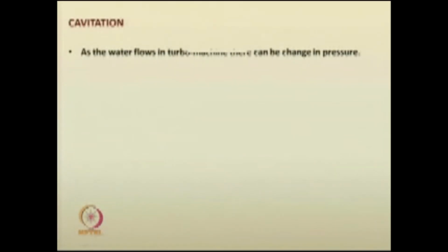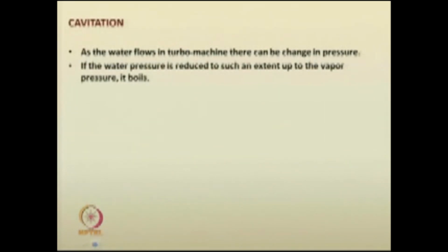Next, we would briefly like to discuss cavitation. What is meant by cavitation? As water flows in a turbo machine, there can be a change in pressure. If the water pressure is reduced to such an extent that it becomes almost equal to the vapor pressure, what happens?